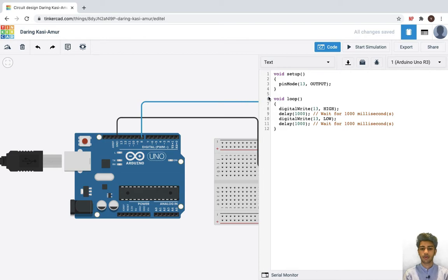So over here, we are going to use our pin 8 as the output where the LED is connected. So I will just change this to 8. This is quite similar, if not completely similar, to the program that we just wrote. That's why I'm not going to explain the flowchart all over again. But it is exactly what we want to do. We want to turn the LED on for 1 second, wait for 1 second, turn the LED off, wait for another second, and put this in a complete loop.